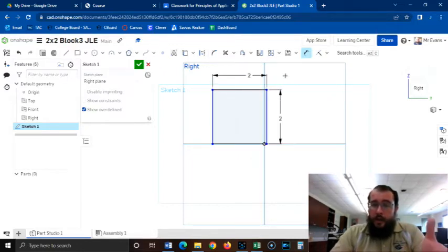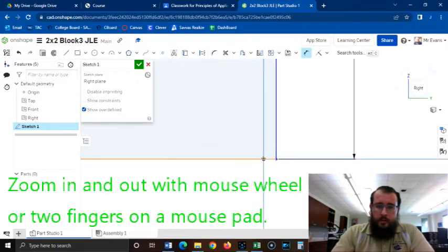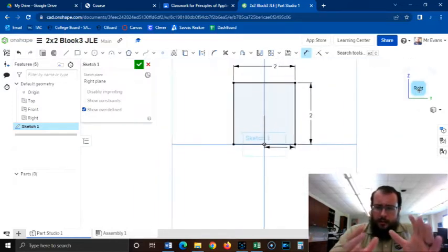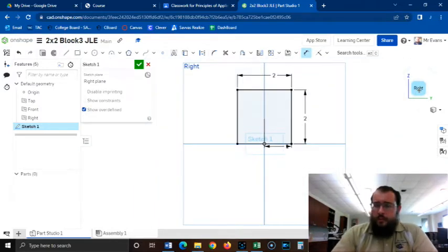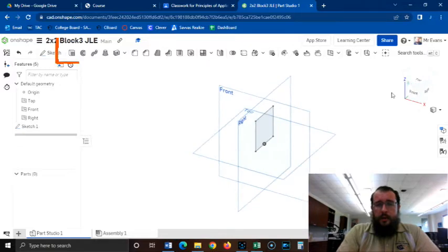And you know what? I'm going to add a third dimension here because I don't want it to move over like that. So I'm going to click here on that point and here, and I want this to be 1. I want it to be kind of centered. Things work nicer when you're able to center them or direct exactly where they are. So I'm going to hit OK on that, and I come and click Edit an Angle.